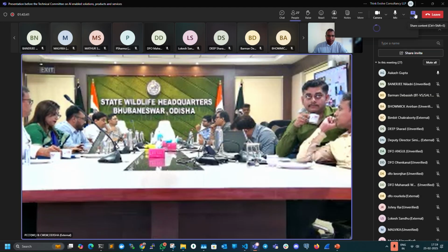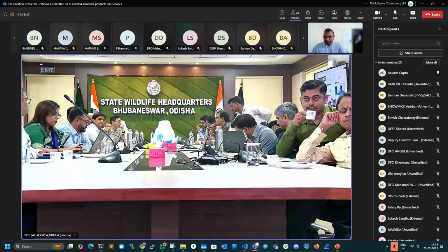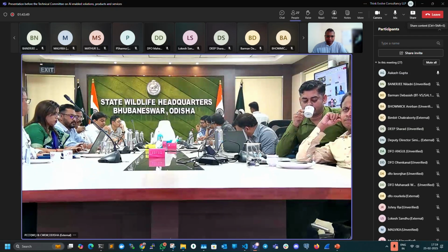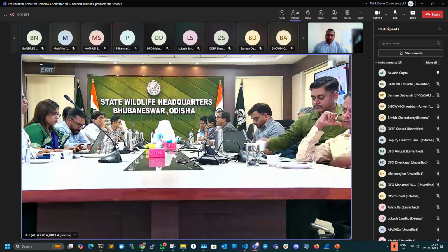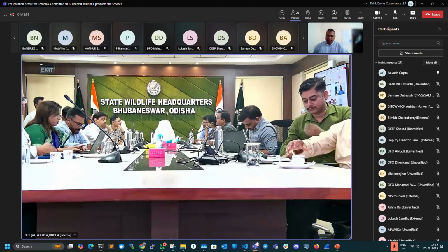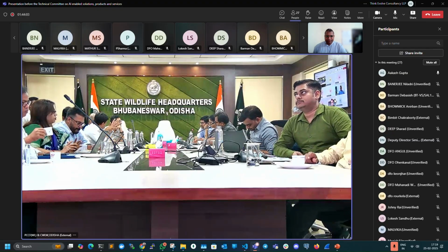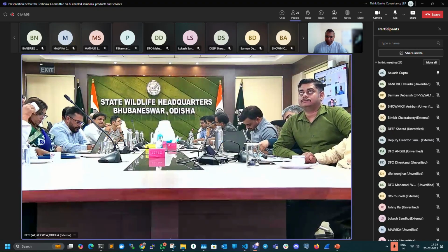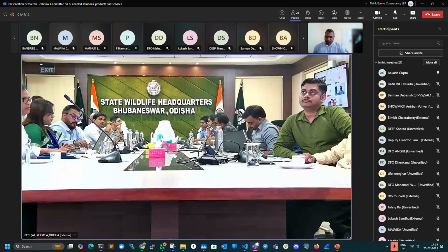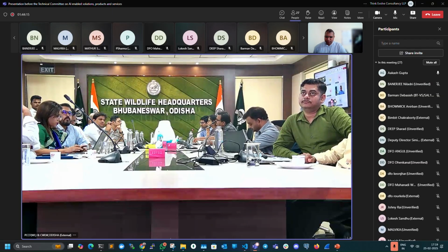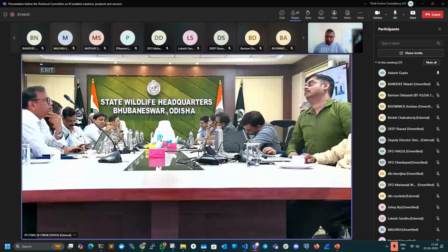So you have this intrusion system as well, right? Yes. Meant for intrusion. We have a classic issue in Odisha. We have a high elephant conflict in certain districts. So we want a system where, in a village, for example, we geofence the entire village with sensors. But it should not give a false alarm. It should only take the height of the elephant, maybe a big adult elephant of 8 or 9 feet height. We geofence it at around 8 feet or so. And then that sensor should be able to capture that elephant, detect the intrusion and send the alert.